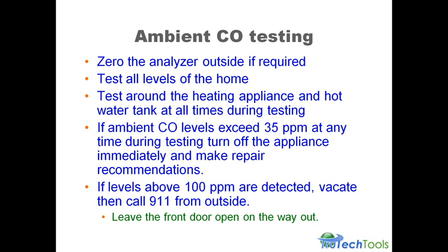Now the homeowner has the right to tear your tag off and relight their appliance and restart it. Well, hopefully they don't do that. But you sign off, and typically when you're talking about a tag for that, you're going to want a 3-part NCR tag. You're going to leave 1 copy with the homeowner, 1 copy with you, and you should give a copy to the jurisdiction having authority, which is typically your utility.